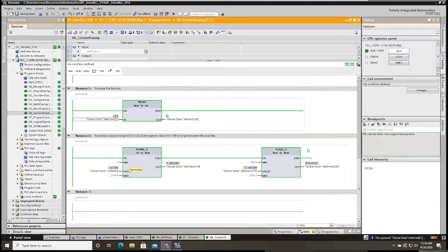You can normalize and scale values. For normalize, you define your minimum and maximum, and then your actual value. It essentially takes whatever range you give it and pushes it to between 0 and 1, which makes it a percentage, basically 0 to 100%. And then there's scaling. You'll see that they scale this value between 0 and 1 to a percentile, and they scale the lower bound 0% to 100 and the higher bound 100% to 500, which more or less manipulates that value.